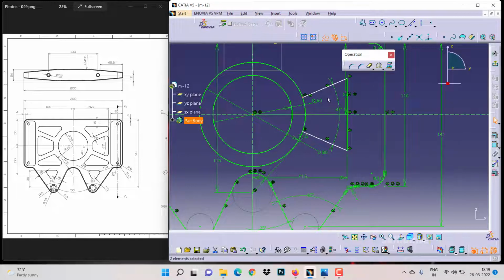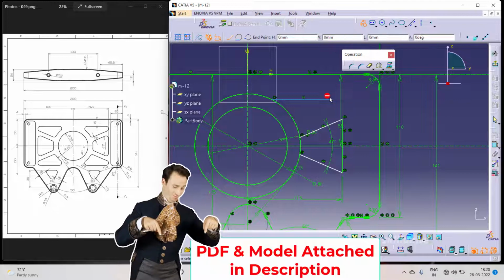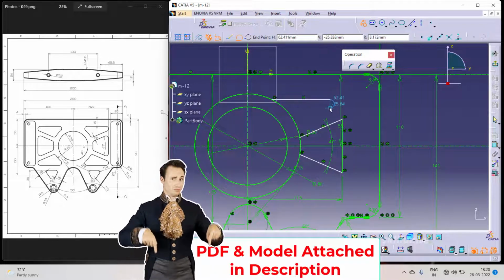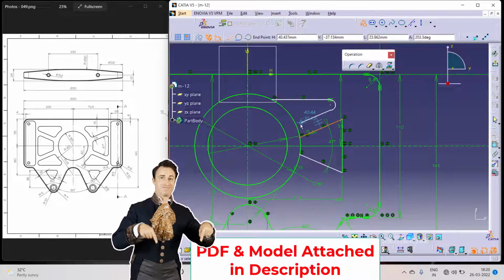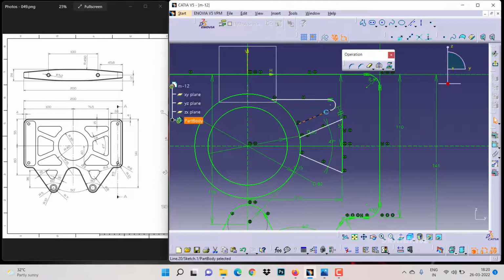So for making this fully constrained, we will create this top shape we are having, then we will make it fully constrained. Click on this option over here, then select the line command. Go straight because it is going to be a straight line. Then there we are having an arc, so make an arc, then connect it in an inclined manner with the edge over here.